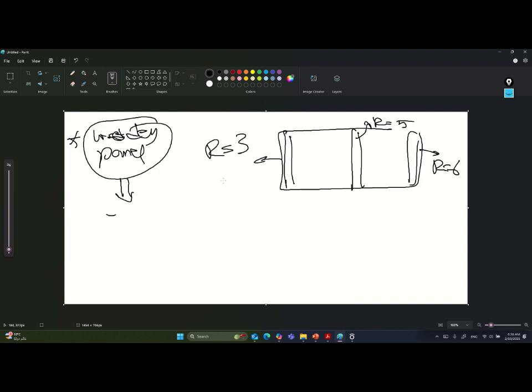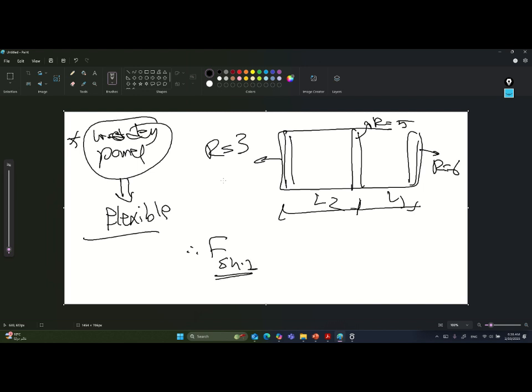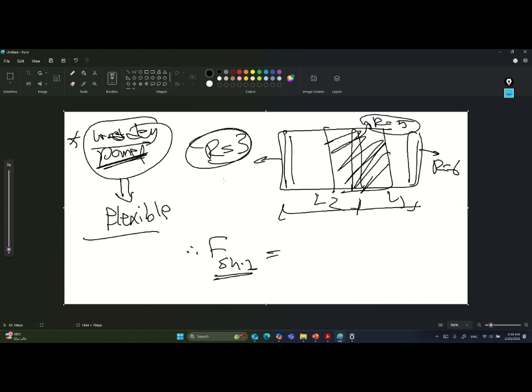Wooden means flexible. So I still have my L1 and L2, and the shear force for shear wall 2 is still based on the tributary area. He gave me the rigidity, but it is a wooden panel. It doesn't matter if he gives you rigidity, even a very extreme rigidity, the forces will transfer from the wooden panel, the diaphragm, to the lateral resisting system. So it is still flexible, and still based on the tributary area.